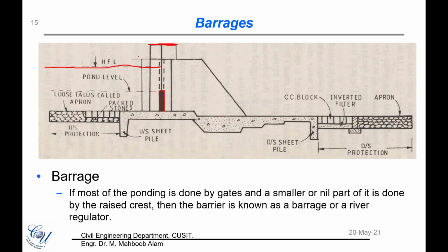You should consider here that in case of floods coming in a particular stream or river, the mechanism of working for the weir and barrages would be very different. Once a flood comes and let's say we have a weir there, the weir is mostly an uncontrolled structure, which means that once the water level reaches the top of the crest, it would start flowing downstream.